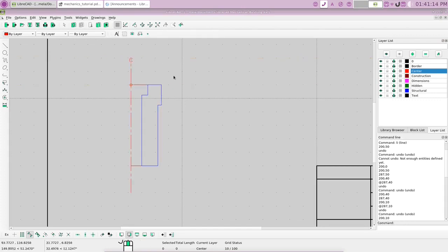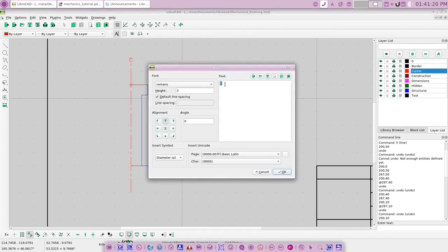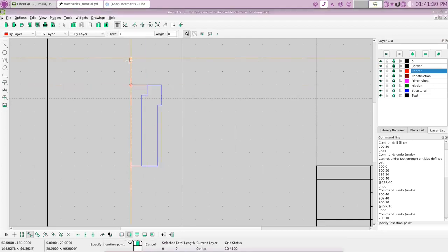Okay, right mouse click once more, and from the menu, choose M text again. Let's put a capital L there. Okay, again 3 for height, that's good. Angle, we don't need an angle. Say OK. Now, that's going to jump up to the end snap again. You don't want that. Take the end snap off and choose free snap. Now you can put the L right where you like it, and we like to have the L just lapping onto the C like that, okay? And that designates that this is a center line. Okay, so now the center line is complete.